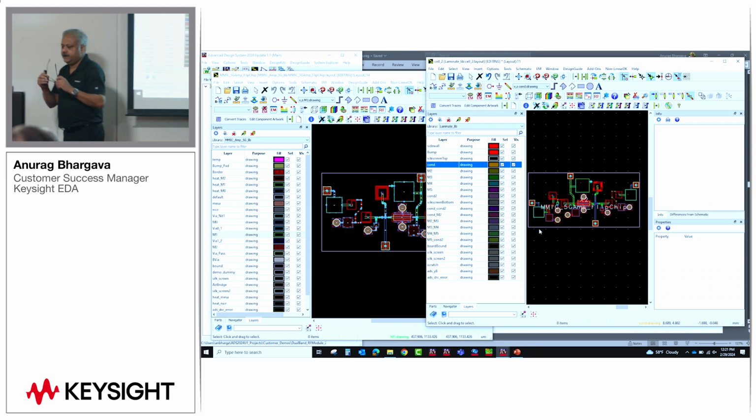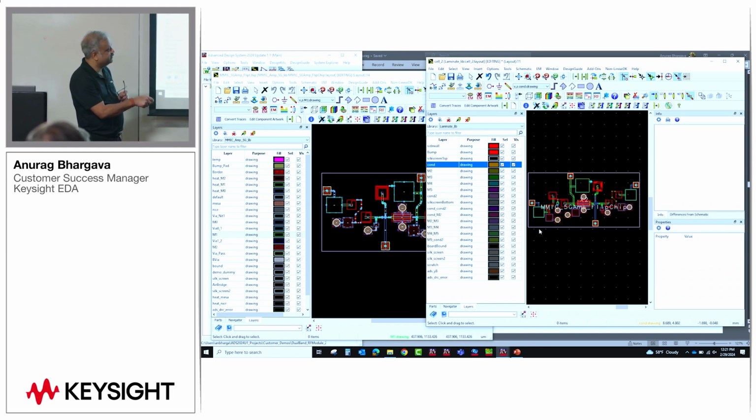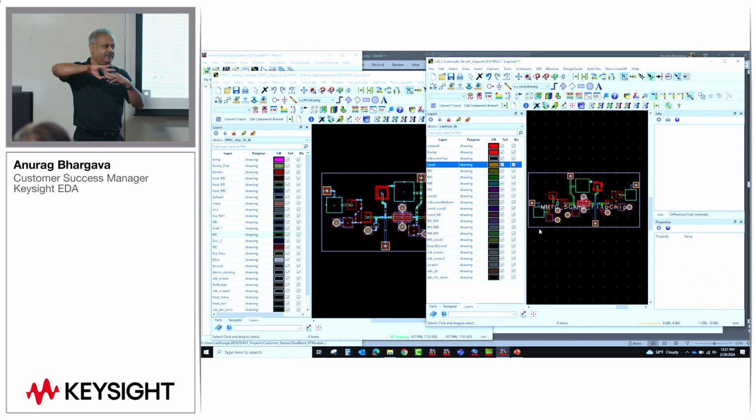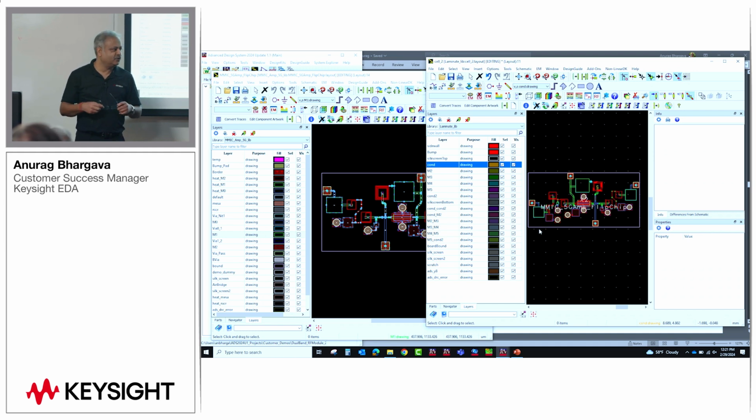All right. And another nice thing is the stack up of this IC, when I go to EM analysis, will also be flipped automatically. You don't need to manually create a flipped stack up so that you can do a composite stack. Once you mark this as a flip chip smart mount, everything else will be taken care of by ADS. You don't need to bother. Again, the idea is not to cause extra work for the designer.